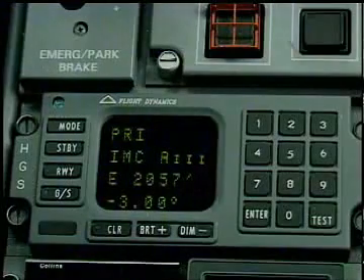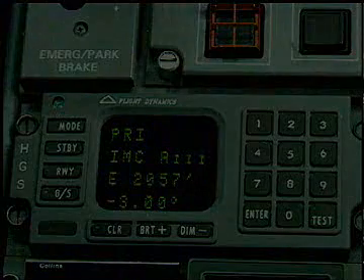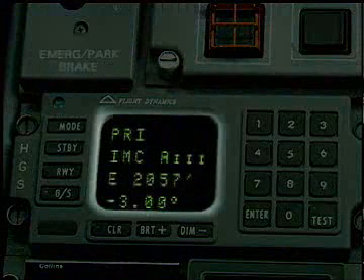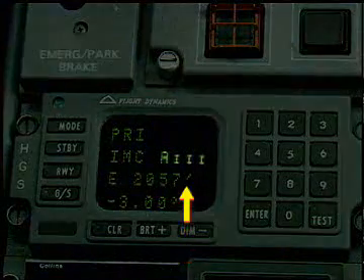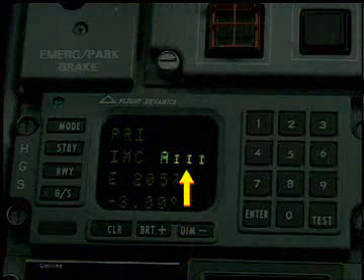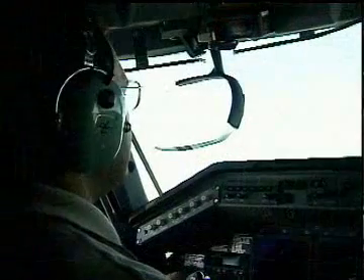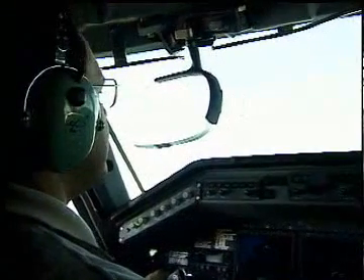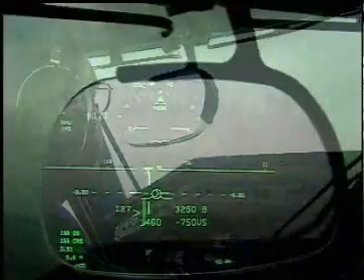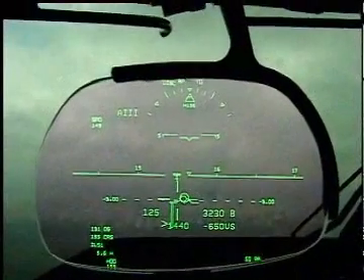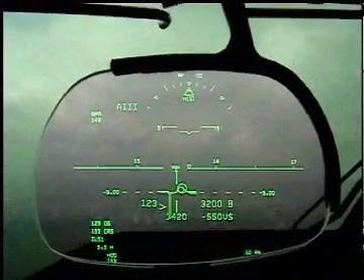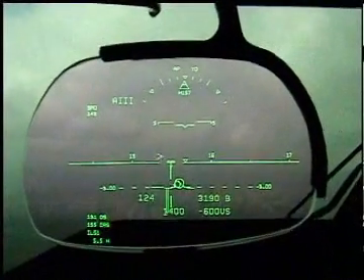A3 mode requirements. Prior to an ILS capture, the ability of the HGS to calculate and display A3 approach guidance is indicated when A3 is displayed on the right half of the HCP standby display line. This display indicates that the HGS and related sensors are operating normally and in the correct mode, and the flight deck is configured for the approach.